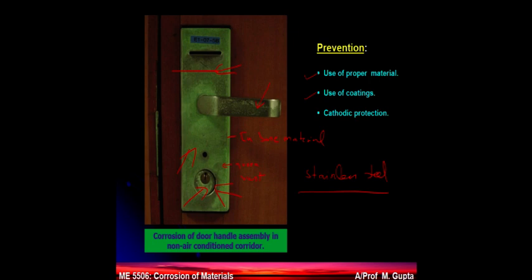And if your structure is quite big, like it happens in the marine condition, that at times you don't have a choice but to use a material which will corrode if you don't make an intervention, then you can use cathodic protection, which I will explain in detail. That is nothing but attaching a more reactive element to that structure, so invoking the galvanic corrosion principle.